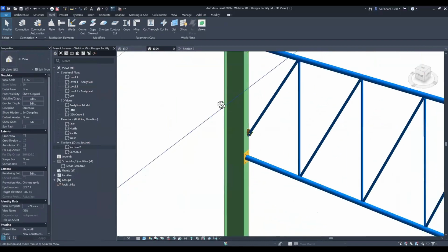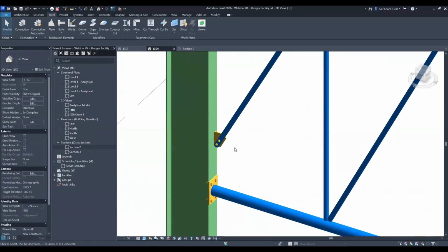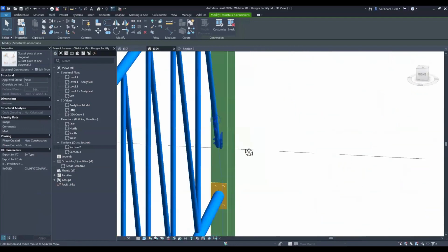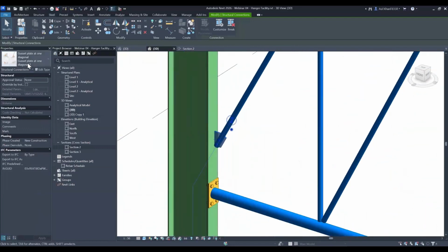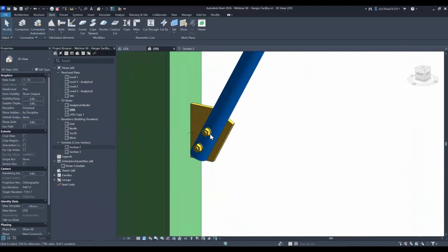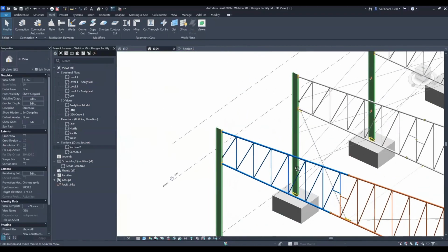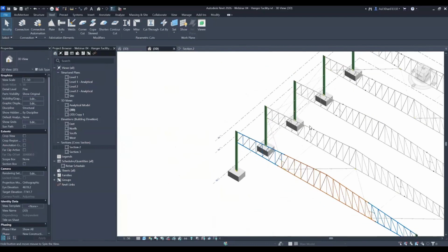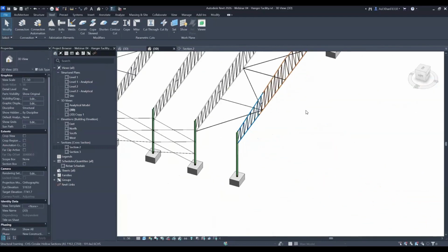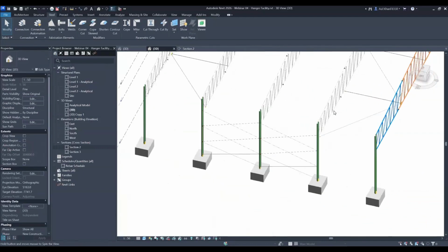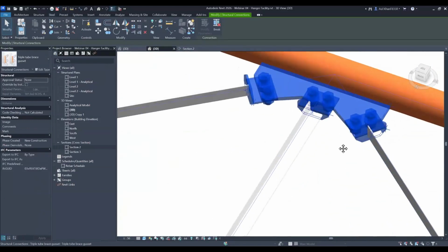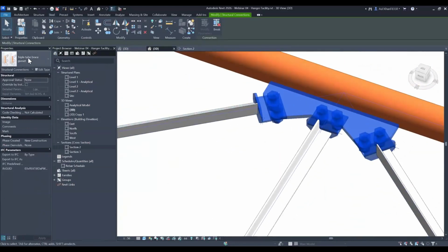So endpoints are connected by the plates and bolts, and this web member is again the same situation, diagonal gusset plate with one diagonal, and I just put the bolt over here. If you want, you can remove it and weld it directly. Great. And in some cases, for example, over here, we put some horizontal lateral bracing, and two types of connection I have shown over here, which is tube to tube brace with gusset.